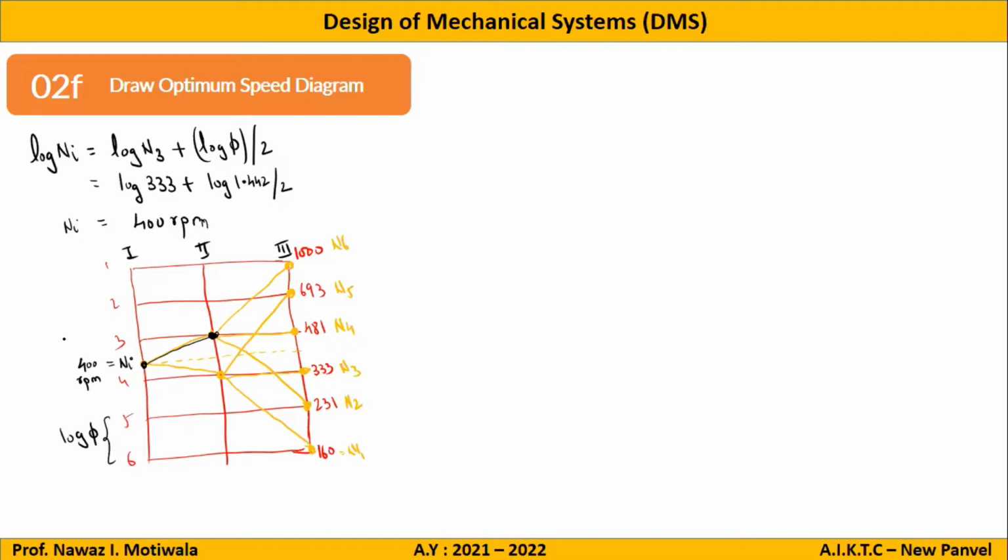No, because I already explained that for getting these speeds which I have written, the input shaft speed should be how much? 400. It is written there as well. Now I have a motor of 1440, and I need 400. What will I have to do? I will have to put in a gear.